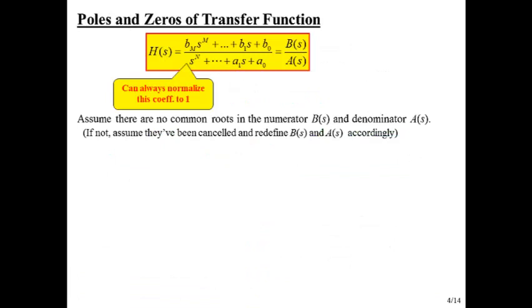So once we have that transfer function, whether we got it from the differential equation or from analyzing a circuit, when we get it like this, it'll be a ratio of two polynomials. I'm showing it here in standard form. And then we can identify the numerator and the denominator polynomials. And unlike in the Z transform case, we don't have to worry about any z to the power terms sitting out in front, and we also don't have to worry about Z inverse form versus Z form. In Laplace, it's just s. We'll always end up with s's.